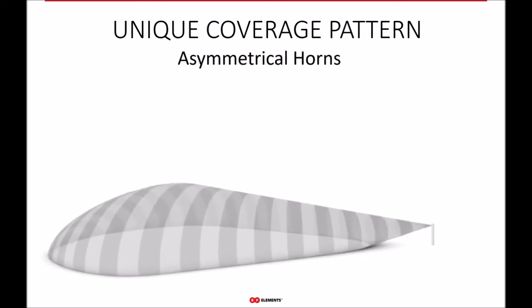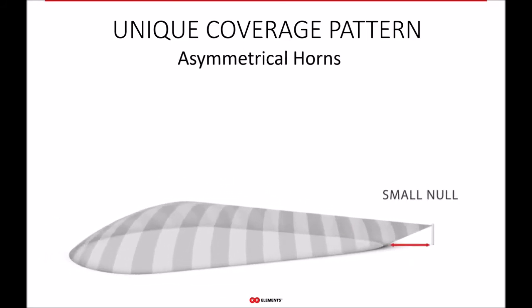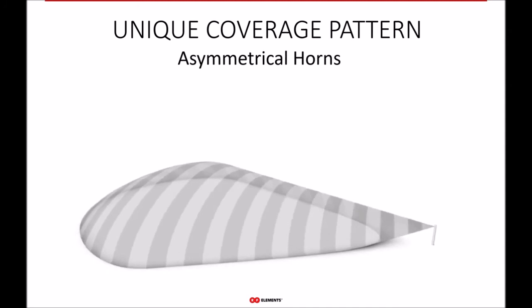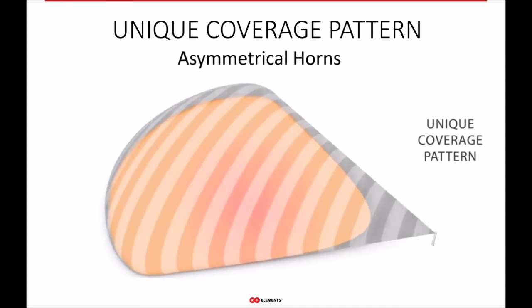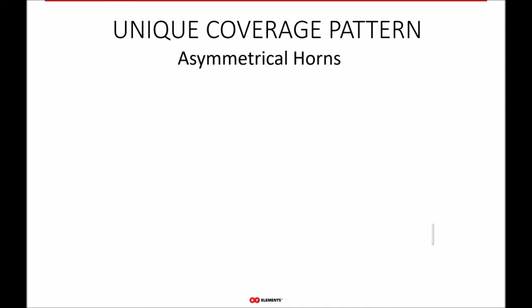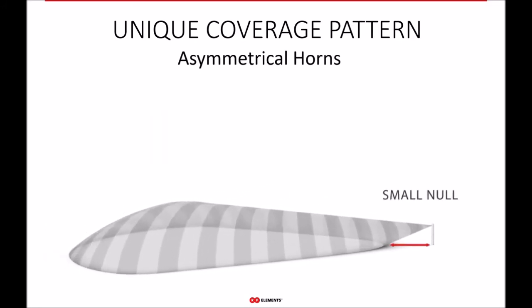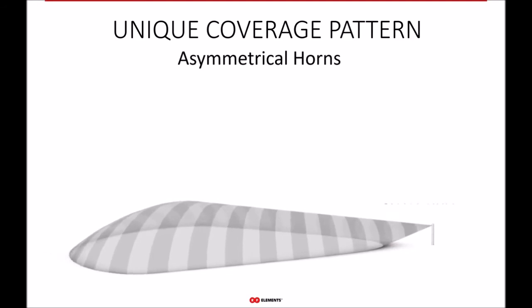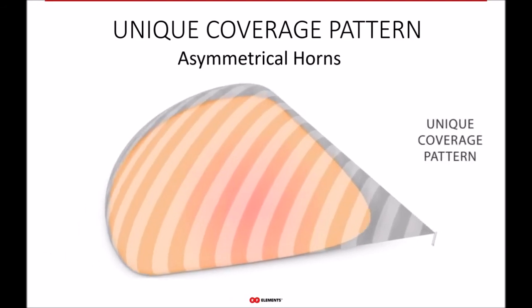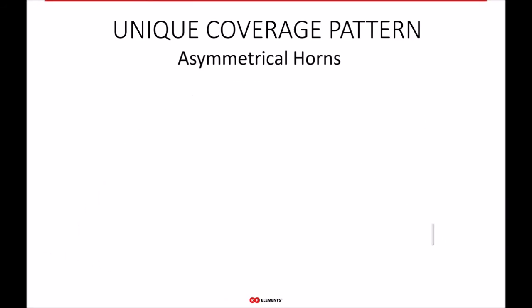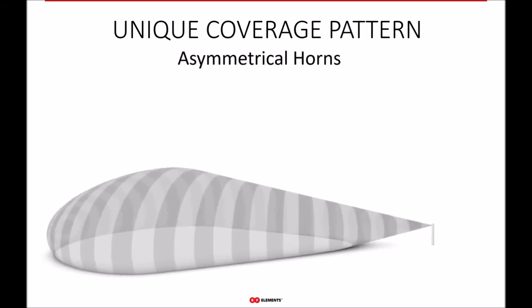In general, the radiation pattern of a horn with more width in the elevation allows for much better coverage of the null areas near the site. Again, that's just not possible with the traditional patch array sectors. And here we show how it works with the asymmetrical horns, when they are squeezed on either side.